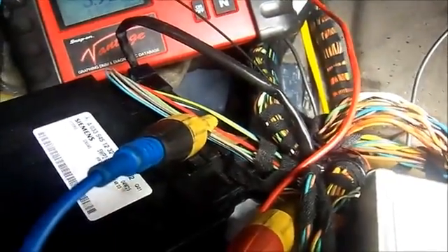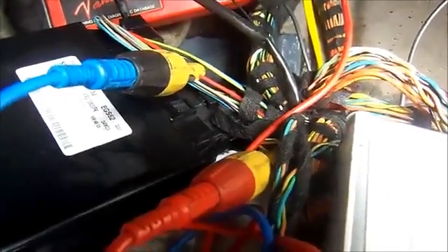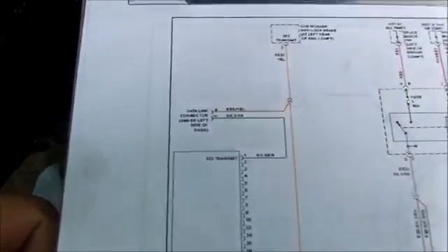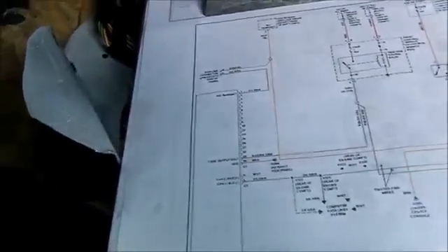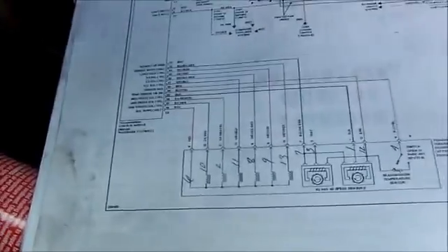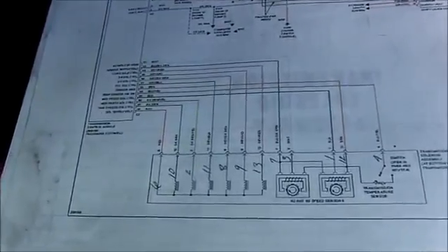And basically on one connector you have only 3 wires going in. You have a power and the ground, and the SCI transmit that goes to the data link connector. The dark green is the leftover wire. You see we got 1, 2, and 3 wires going into that one connector, and then the other connectors go to the transmission assembly.